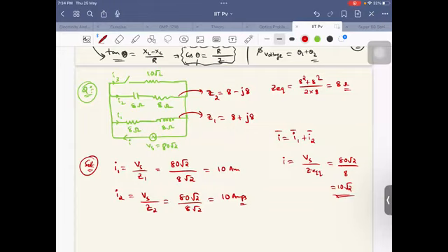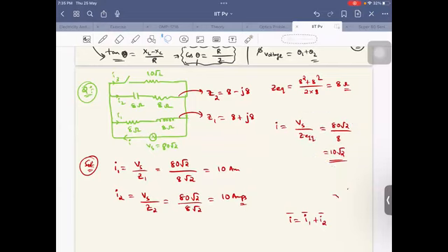But just to give you more clarity, I want to solve this by this method also, so that you will get more and more clarity. These currents are phases. Whenever I want to add them, not only currents, the voltages also, this Vs can be written in this way also, plus minus Vr, plus minus voltage across resistor, plus minus voltage across inductor. So Vs can be written as Vr plus Vl, but these are not scalar sums.